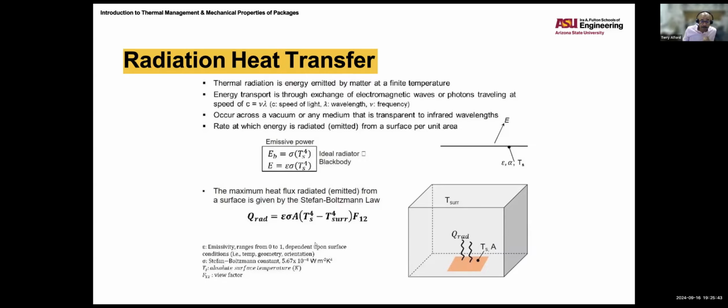All right, so again, know that there's this concept of thermal resistance networks, and if you can use the assumptions for 1D, it works out just like a simple electrical circuit. Okay, even though we can do modeling and design, we still need the thermal characterization, and we need them to work hand in hand, design and experimental validation.